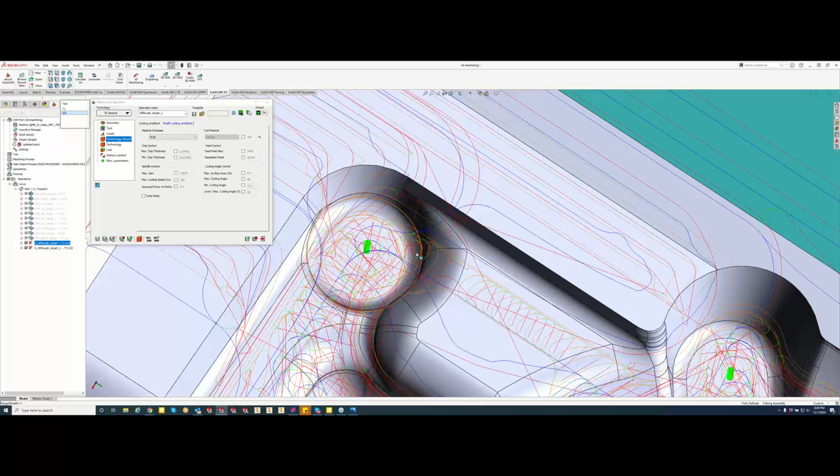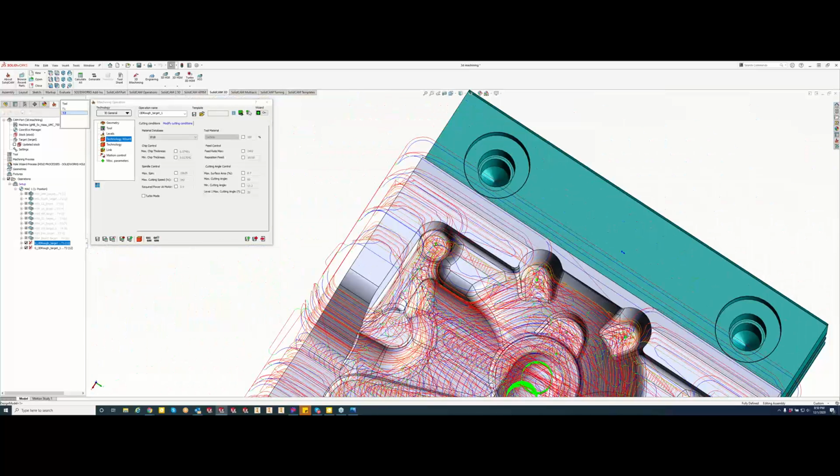But back to Brendan's point with the faster cycle times, you will also see a longevity of your machine just because we're not ramming that tool into the corners anymore. So it's going to be much easier on the ball screws of your machine. So in my eyes, it's a win-win all the way around because we're going to save your machine life. It's easy to program, as well as get better tool life and decrease the cycle time. So quite a few different wins there.